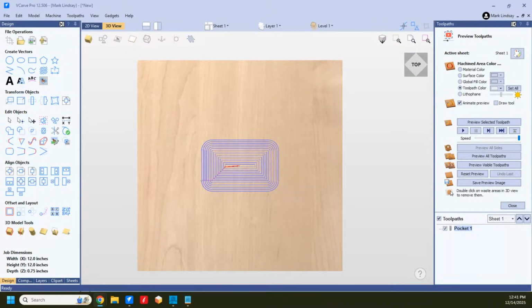There are a lot of folks who can run certain materials really fast, me included. But if I'm cutting highly figured maple, or particularly hard maple or purple heart, the material won't let me cut that at 300 inches per minute. It just won't. Where I could do that with pine or something.